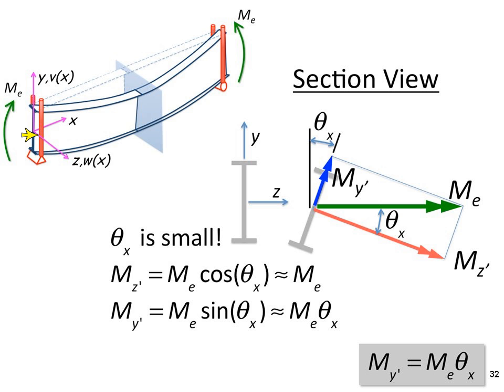And sometimes you see this happen when it's horrible, they're placing a big, deep bridge girder, and they don't torsionally secure it at its ends before they release the hoisting cable, and just as a result of its own self-weight, the whole section just literally starts to flex, starts to pick up a torque, and the whole system just literally tips over. So yes, there is a resisting torque at the ends, but it's not impacting our solution.